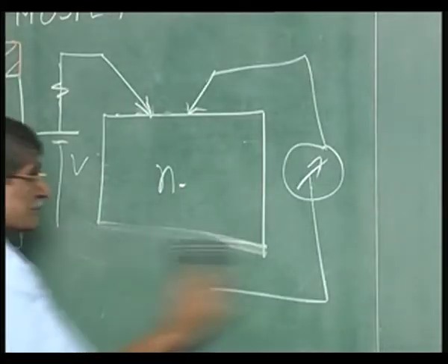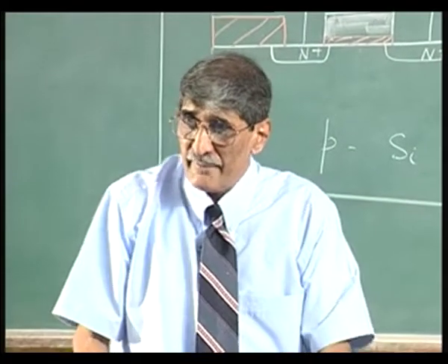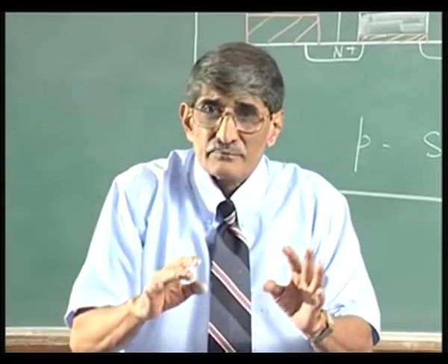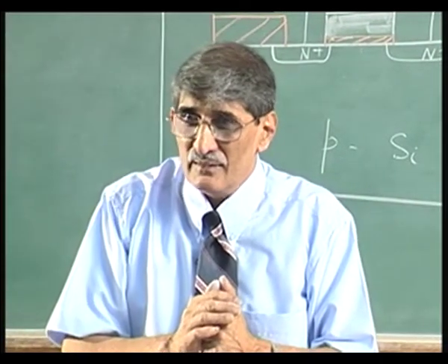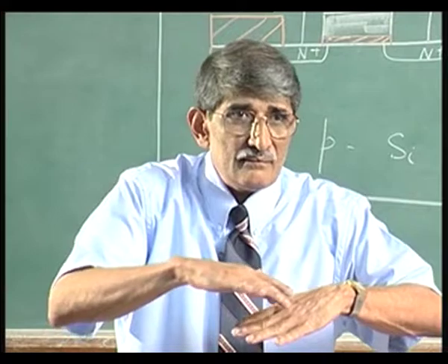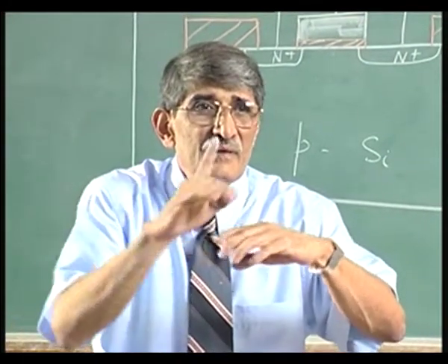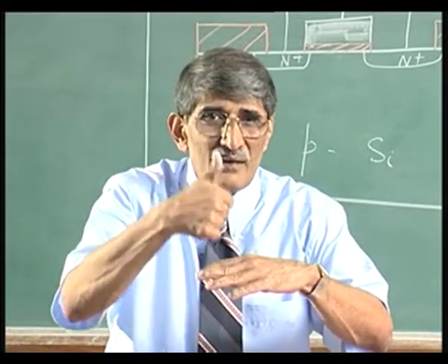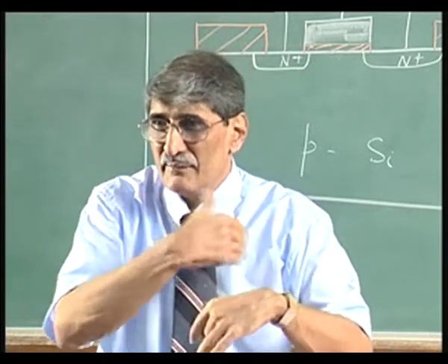Now, let us see. So, on a free surface a problem is there. When you have deposited oxide, there will still be problems. If it's thermal oxide, the problem is not there, because those interface states, after all, what are those states, surface states, due to? The atom within the bulk is surrounded by 4 neighbors. When it comes to the surface, on the top surface, it is 1, 2, 3 neighbors. Up there is no neighbor, so there is a dangling bond. The dangling bond is the one which gives rise to the levels.